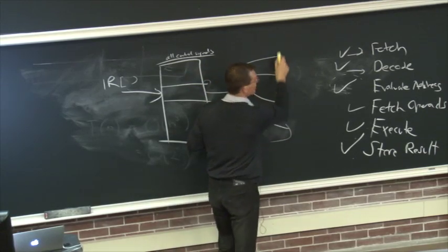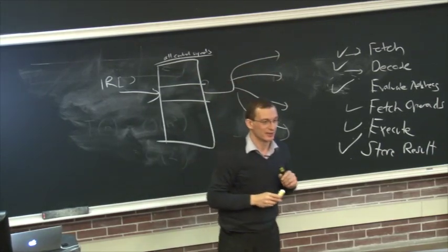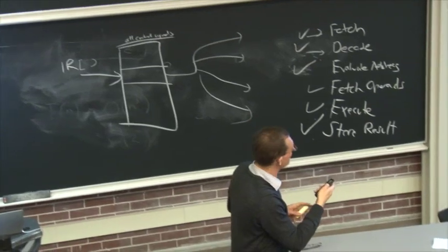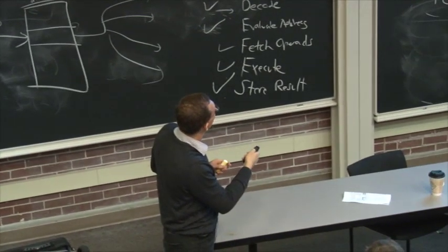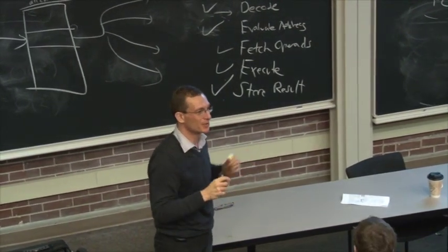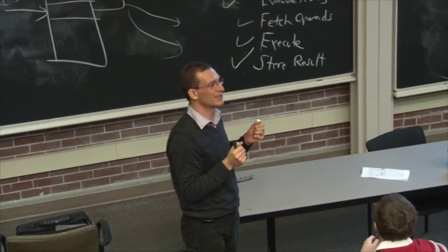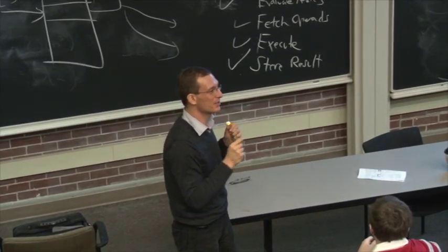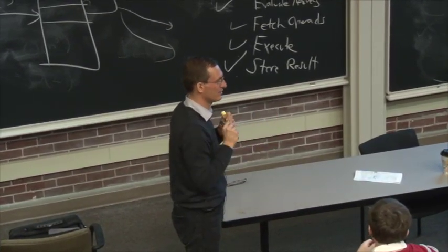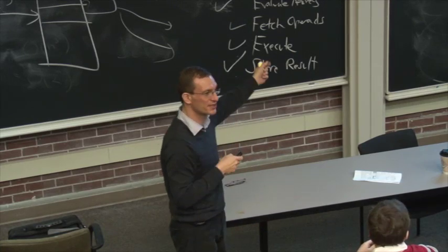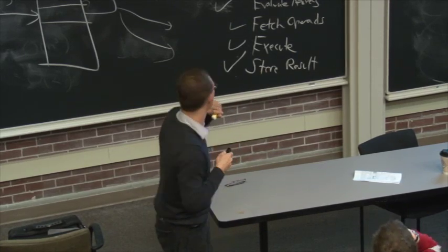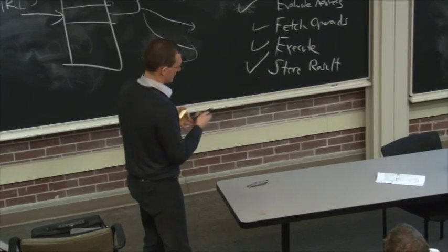Now, modern machines actually employ both. Even if you have microcoded control, combinational logic is almost inevitable. Some functions are a lot easier to implement in combinational logic because you need interaction between the data path elements and control. And we will see this when we cover microcoded machines.